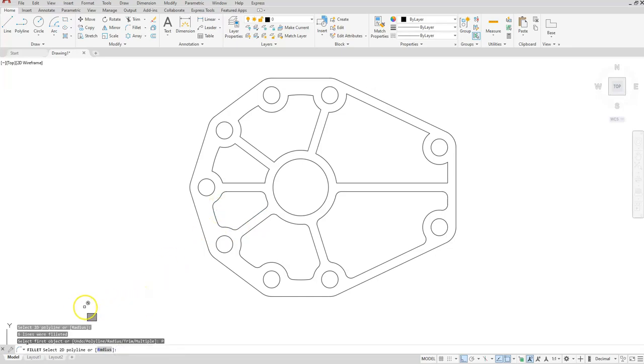Looks like I selected radius again. I'm just going to type in 0.2 again. Select multiple and then polyline. Then I'll keep working this all the way around. So polyline, this one, and our last one is a polyline here.